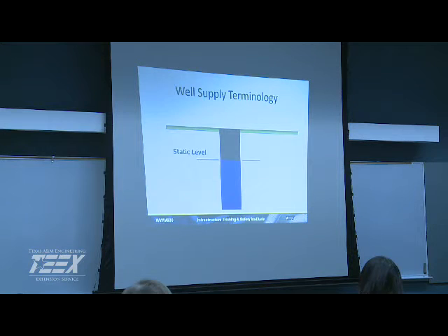So when we're looking at our well casing, when it's sitting still, not running, that's going to be our static level. And then when our well is running, we're going to have our pumping level. I don't know if y'all have a way to measure, but sometimes you'll have a little casing there where you can even use something as simple as a little plumb bob on a string, run it down and measure it, and test it when it's static, test it when it's running.